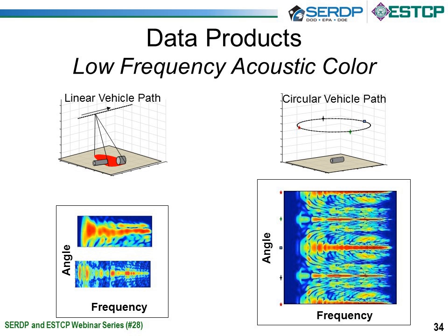In contrast now, when you're doing a linear scan, your look angles at the targets are only determined based on the beam width of the transmitter and receiver, which for low frequencies it tends to be pretty wide. So you may have plus or minus 40 degrees with a total of 80 degrees. And these snippets correspond to segments of the circular scan case around the object.